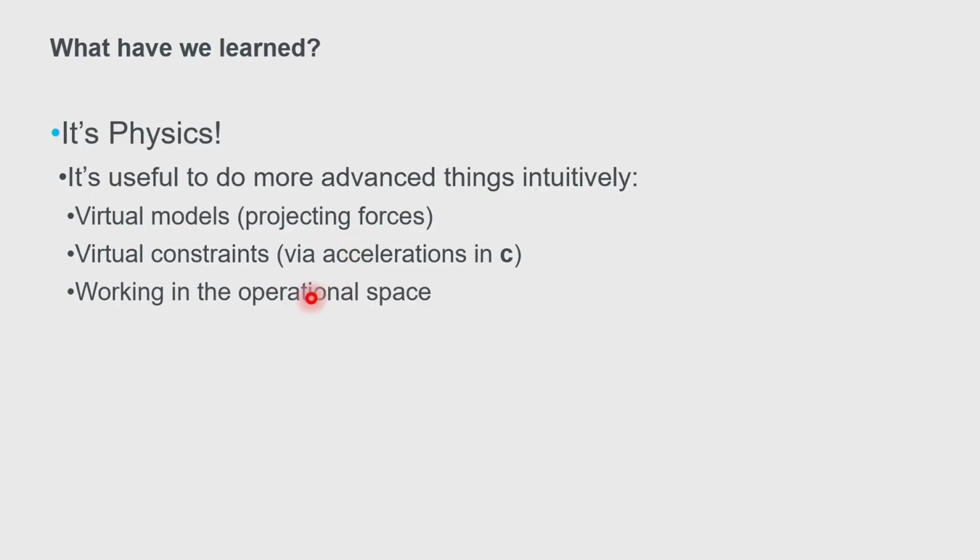This whole idea of working in operational space, I'll share a paper later on, is basically based on this: you want to think about working in different spaces when you have a robot. The most natural is joint space, because that's where your motors and your sensors are. But if you think about your robot doing something useful, often it makes more sense to think about the end effector space. And now, what is the inertia, the masses, of the end effector space?